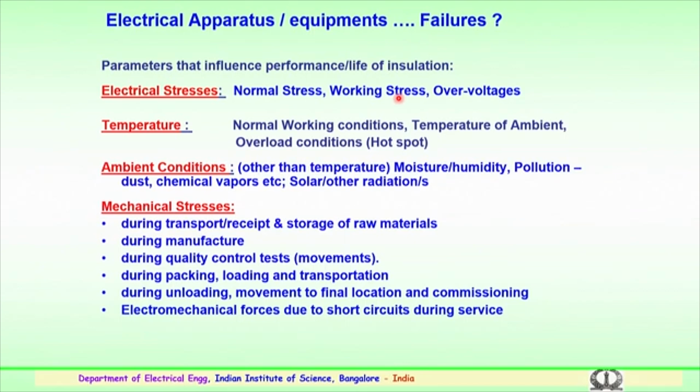The second factor is the temperature. Because of the continuous stress, a temperature rise could be seen in the insulation. This temperature rise is different from the ambient temperature. The insulation should be able to withstand the temperature at which it is working. Apart from that, there are overload conditions. Overload conditions could be because of the addition of loads, or loads being applied at the required levels. So this temperature also changes, and the insulation should be able to withstand this temperature.